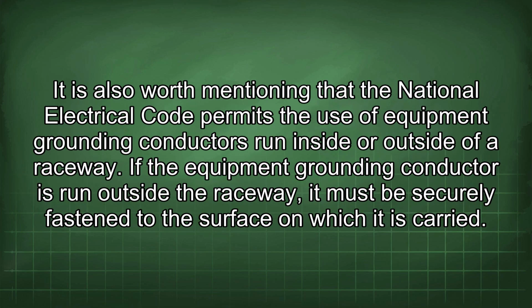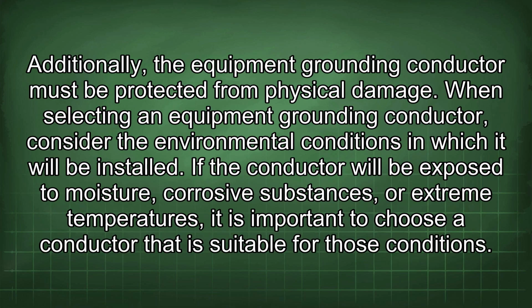It is also worth mentioning that the National Electrical Code permits the use of equipment grounding conductors run inside or outside of a raceway. If the equipment grounding conductor is run outside the raceway, it must be securely fastened to the surface on which it is carried. Additionally, the equipment grounding conductor must be protected from physical damage.